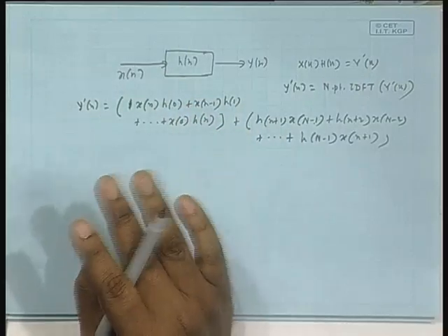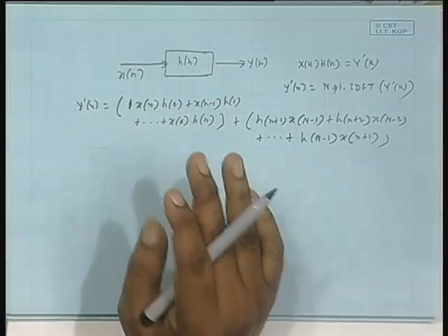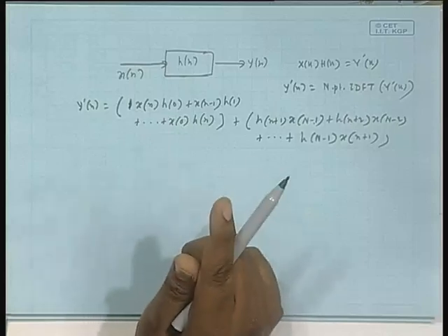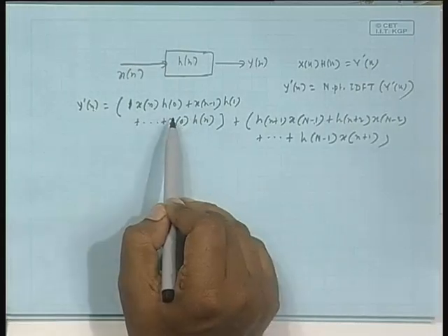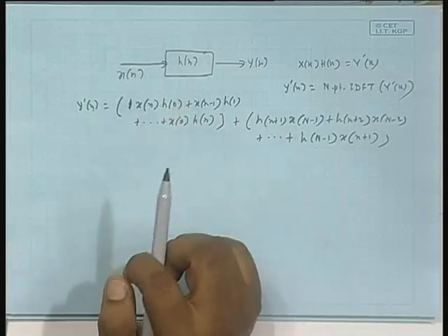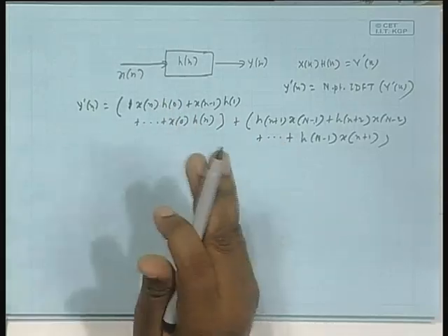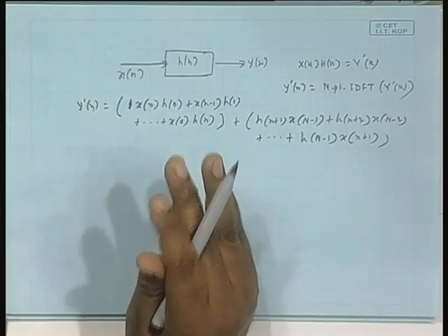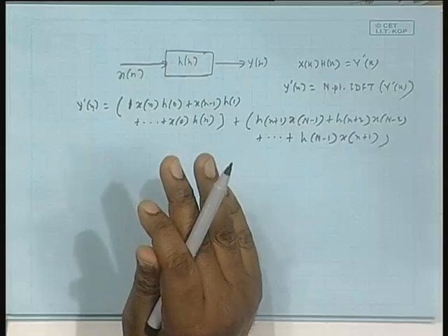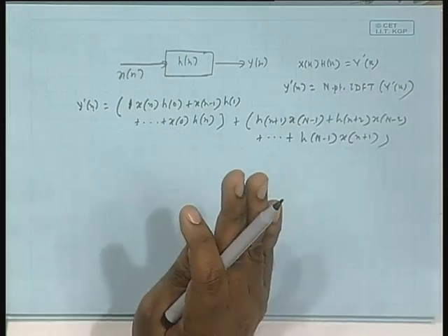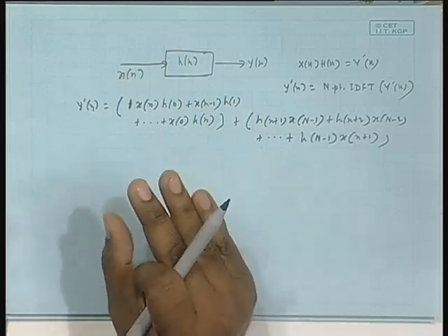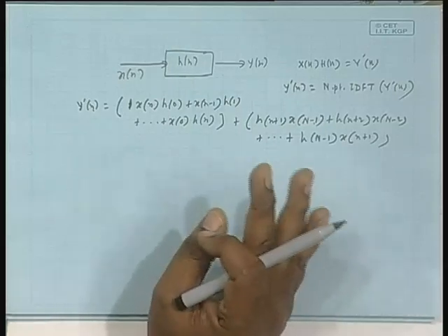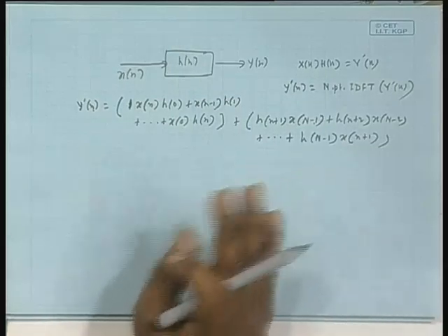And then you shift this by the amount at which you want to carry out the convolution. Like here you are finding the convolution at n. n can be 0, 1 up to capital N minus 1, that is our range. So, shift it to the right by small n. After that you still have an infinite length sequence. Now, you throw away the components outside the window from 0 to capital N minus 1, to the right of capital N minus 1 and to the left of 0.